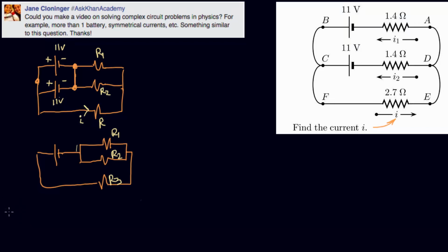Okay, so parallel resistors, R1 in parallel with R2. I made up this symbol, two vertical lines. That means they're in parallel. And the formula for two parallel resistors is R1 times R2 over R1 plus R2. Now we'll plug in the values.